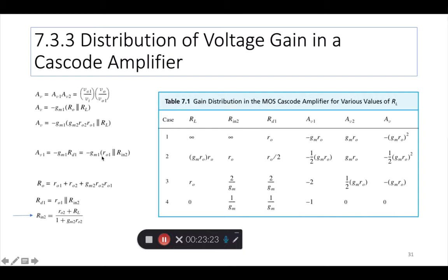All right, because the gain of stage 1 obviously depends on the transconductance Gm1, but also on the output resistance. And the output resistance is not only RO1, but the input resistance of the second stage, the cascode stage, the CG stage, also appears, right?